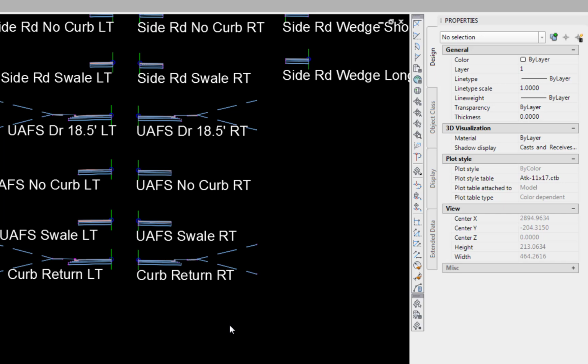also known as the spandrel portion of the cross gutter, and the gutter in the curb subassembly has a length of only 1 inch. The top back of curb, which contains the alignment and profile for the curb return, is located at the assembly marker. The right curb and right lane subassemblies are used for the left curb return assembly, and the left curb and left lane for the right assembly.